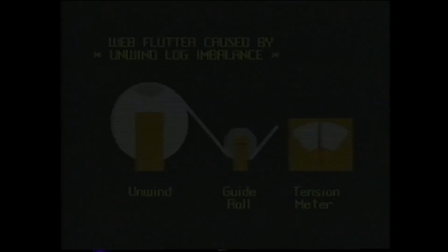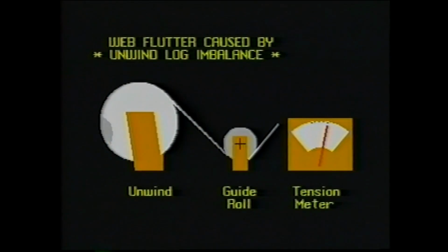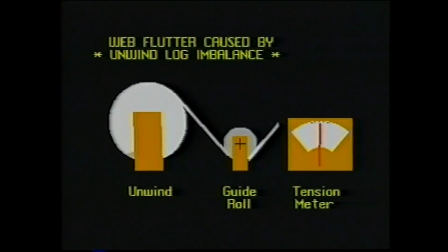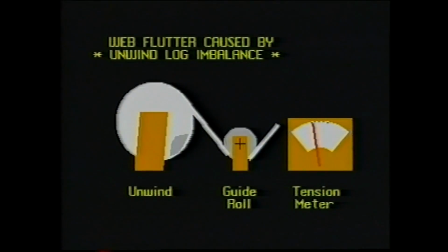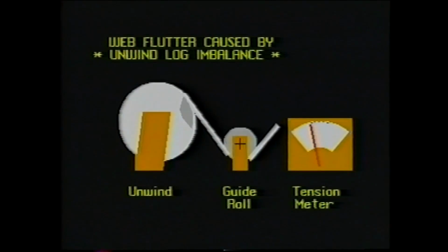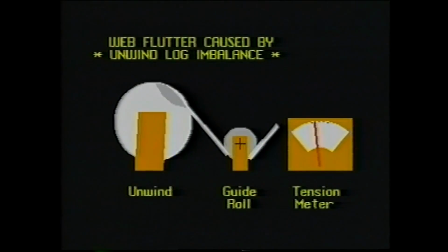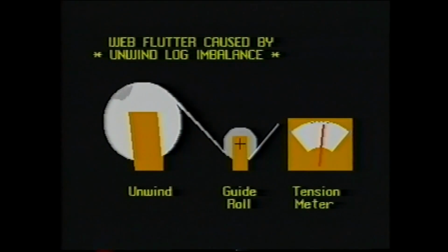Vibration causes include roll imbalance, which produces a once-per-revolution forcing function that can excite a structure to resonance, and roll-sidedness of paper rolls, which are neither concentric nor round. Small bumps or sides on unwind rolls cause web tension fluctuations, and sided rewind rolls cause wind-up station vibration. The unwind is the single largest contributor to web instabilities such as sheet flutter and snap-offs. Resulting problems also include rough slitter cuts, ragged roll edges, and the need to limit operating speeds.